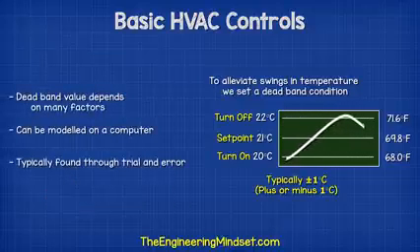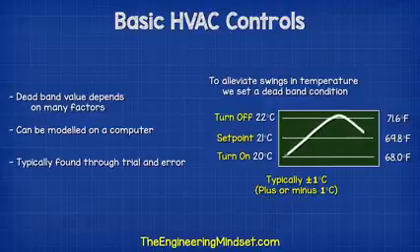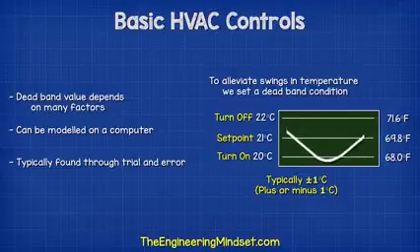The deadband values depend on many factors. It can be modeled on a computer, but generally it is found through trial and error, with small incremental changes to find the optimal point where the room is comfortable and the system operates efficiently.